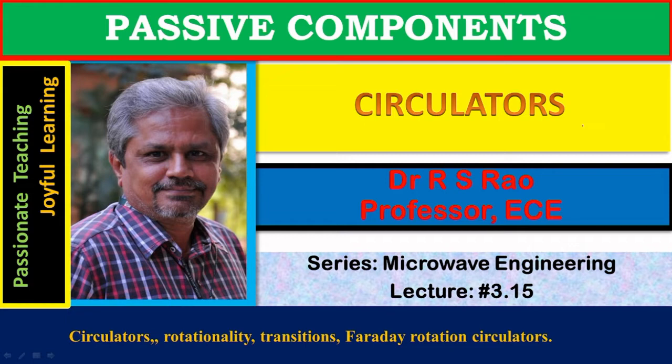Three ports are quite common in these devices, and more than four ports are quite uncommon. They employ ferrite rods for their operation. They accept power at one port and divert this power to another specific port.